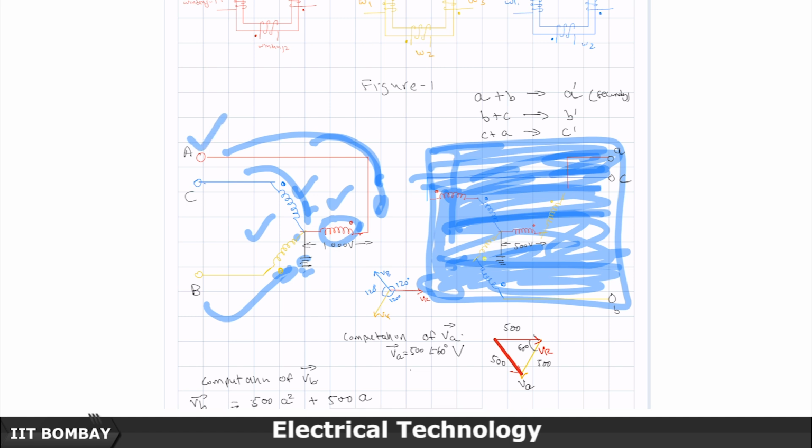We have connected the phase to ground through a leakage impedance, and this has created a problem. For the time being, assume these windings were just not there. So, you had three reactors basically on phase A, phase B, phase C. You created a ground out of them and connected it. Then these reactors, according to their leakage impedance or designed impedance, usually 10% on the rating, will draw a large amount of current, and that is not what we wanted to do. We just wanted to provide some kind of protection application. So, such a simple connection will not suffice, and we have to resort to